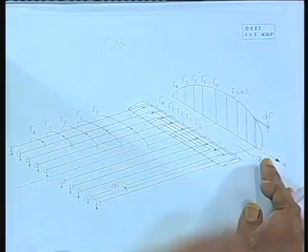Now, there is an advanced theory, more advanced than that, where we think that the propeller circulation also changes along each element, across it, that is chordwise, that is called the lifting surface theory, but those are more advanced and we will not go into that. If you have to do propeller design, then the most commonly used propeller design theory is the lifting line theory based on the principle I have just explained. Thank you.